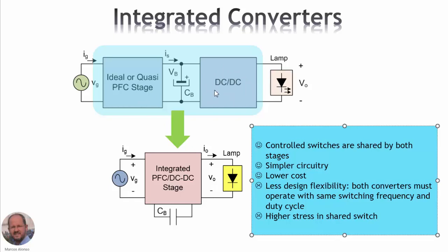So this second converter can compensate variations of the voltage across the bulk capacitor, and then we can reduce the value of this bulk capacitor for a given current ripple through the LED. We know that this is complex, we need more components, more integrated circuits, and so on.